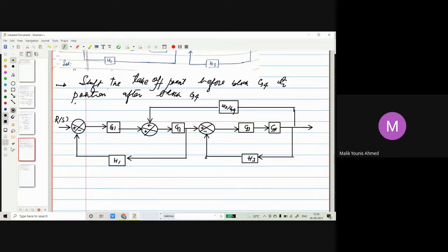So now this is in cascade and this is a negative feedback loop. We can solve it at one place very simply. I don't need to write that. So let us do it. Copy this side. This side we are not changing anything. This side we don't change much, but on this side we'll eliminate this negative. G3 and G4 are in cascade now. Multiply them, and then we can take a closed loop. Negative feedback loop is this closed loop. The feedback is negative. So let's copy this. This portion we can copy up to here.